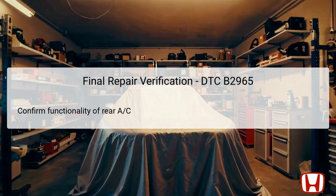The technician should also rerun diagnostics with the Honda Diagnostic System, HDS, to ensure no new or lingering DTCs are present. A successful verification ensures that the communication issue has been addressed and that the rear AC control unit operates in harmony with the HVAC system once again. This step serves as a closing check to guarantee that both safety and functionality have been restored.